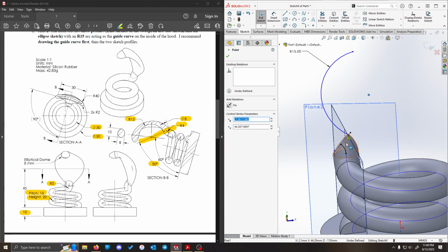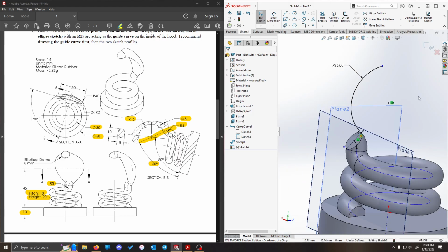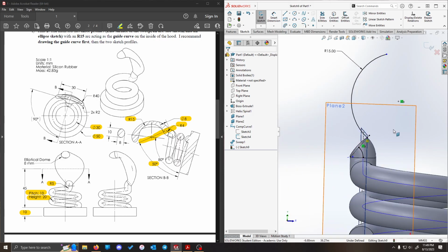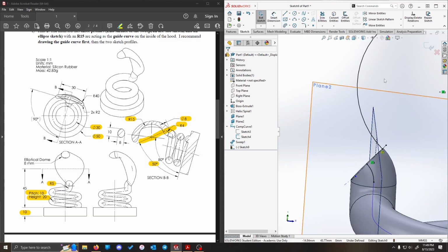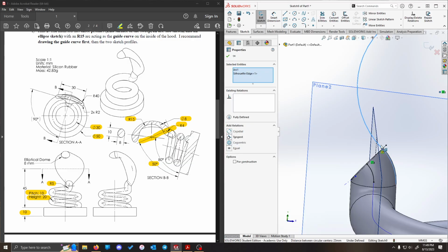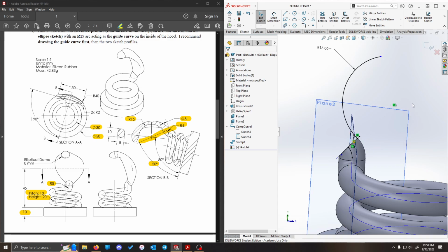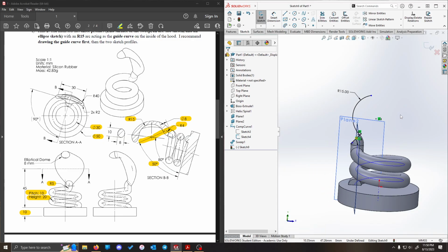Then we can take the end or the center point of our current sketch and the construction line we drew earlier and apply a coincident, which does define our geometry. Following the same geometric principles, if we take our arc and the silhouette edge and apply a tangent, that will define the same thing. So you can pick one or the other, or in this case, both. And because the rules are saying the same thing, they don't conflict, so SolidWorks will allow it.